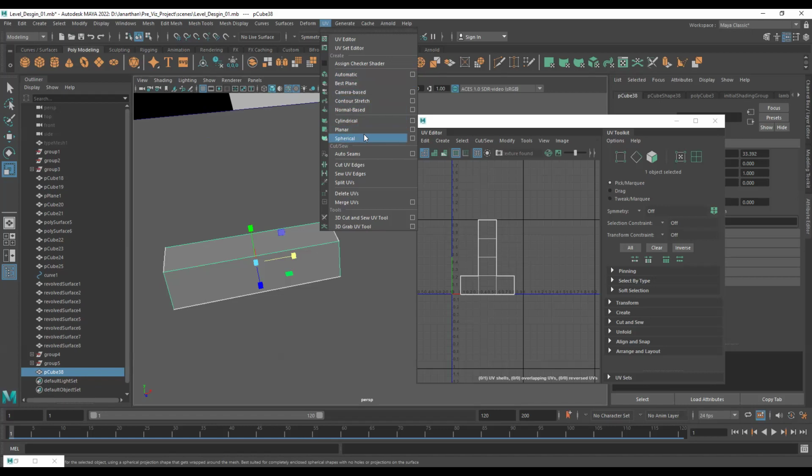Now this box, we can go for a planar map. Suppose you're unwrapping the hand, it looks like a cylinder, isn't it? Legs, cylindrical map. Body, cylindrical map. Head, spherical map. So according to the shape, fingers, spherical map. Okay, carom board, planar map. Box, planar map. According to the shape, we can justify which projection you need.